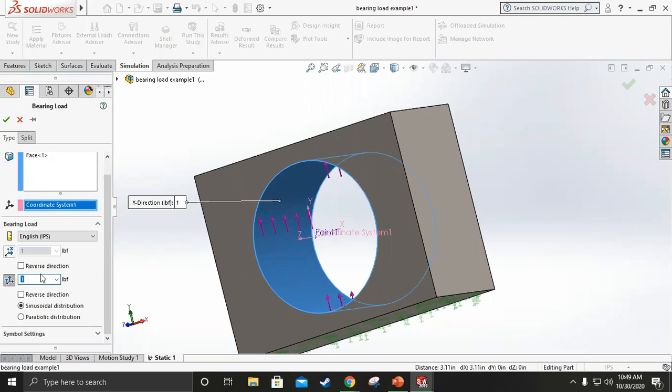How much is the belt being pulled at? In this case, it would be a preload. Imagine a bike, right? And its chain. When you change out the chain, you put it on, and then you would pull the wheel back as much as possible to increase the tension so it doesn't slip off.